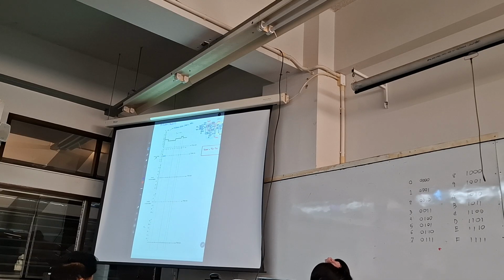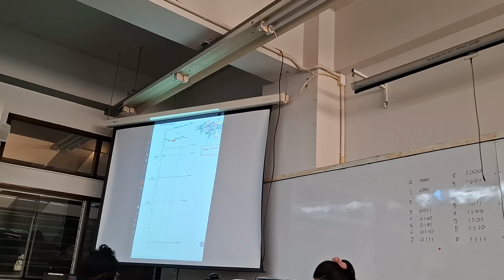Okay, the next step. You have 5, set point minus PV. Set point is equal to 5 volt and PV is equal to 4 here. So 5 minus 4 is equal to plus 1. So in this position you have plus 1.